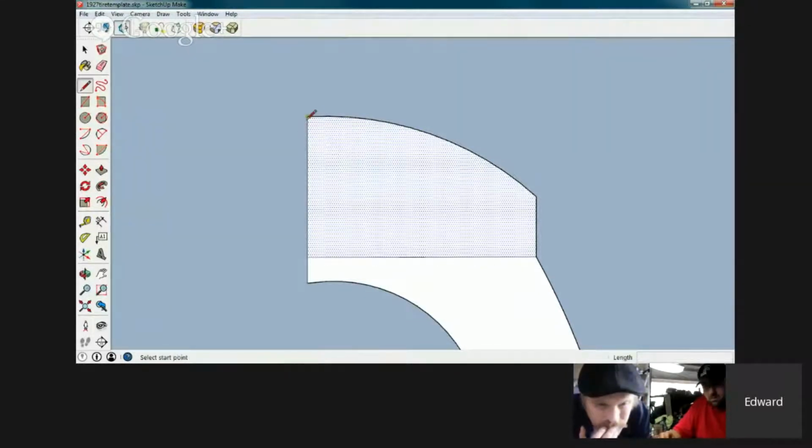So although we had 0.3 millimeter for the wall, the minimum detail is 0.1, and this is where you start playing around with numbers and trying to fake out Shapeways. So I'm going to come down at that 0.1. That's the minimum drop of resin it will actually squirt out, is what they're saying.